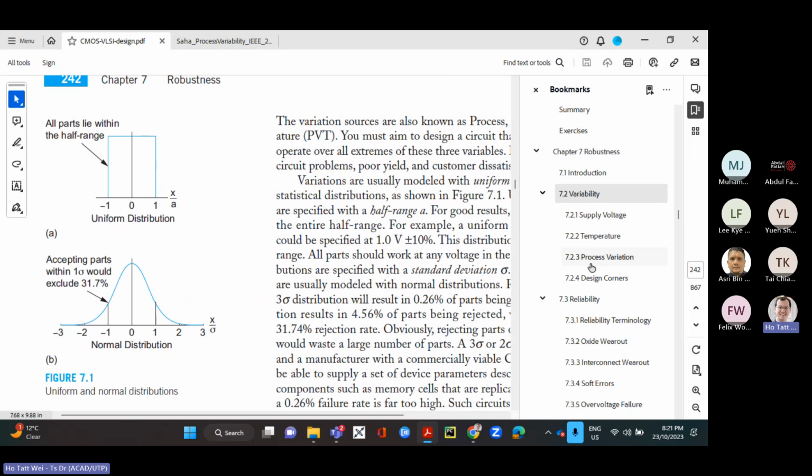So if I were to operate this IC at maybe 5% higher or 5% lower VCC, that variation in the supply voltage itself will also cause variation in the expected performance of the chip, and so will variation in the operating temperature. So if I operate the IC in maybe Antarctica, where temperatures are 0 degrees or sub-zero,